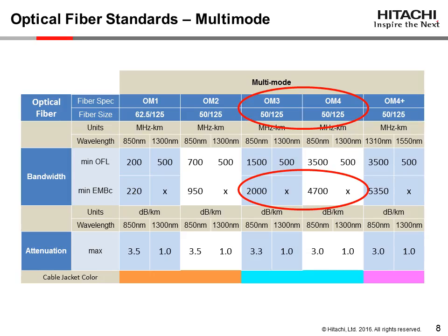This chart shows the minimum bandwidth and maximum attenuation requirements for each multimode optical fiber standard. Optical fiber performance values are set, measured, and normalized at a kilometer distance, 3,280 feet. Taking a close look at bandwidth, the information carrying capacity of the fiber, the chart shows multimode fibers with 2 bandwidth specification categories, OFL, overfill launch, and min-EMBC, minimum effective modal bandwidth calculated. Today, the primary multimode fiber size being specified is 50 micron.